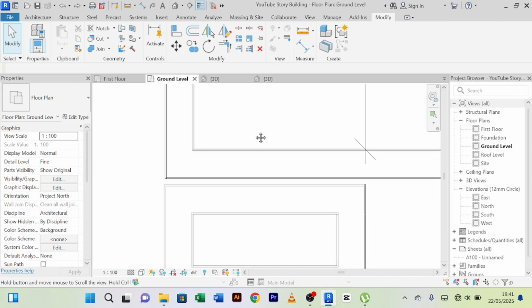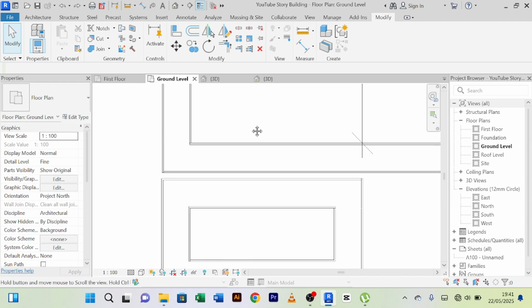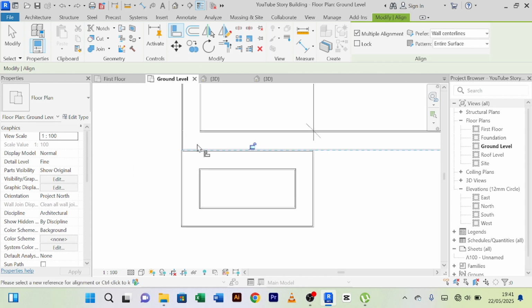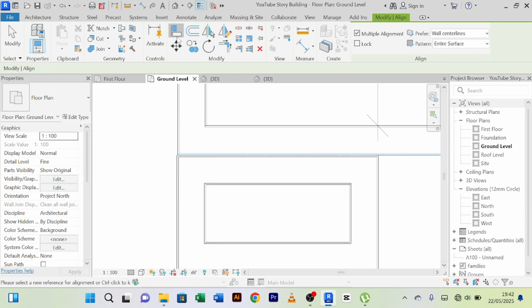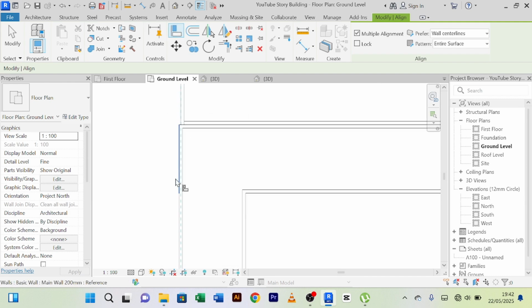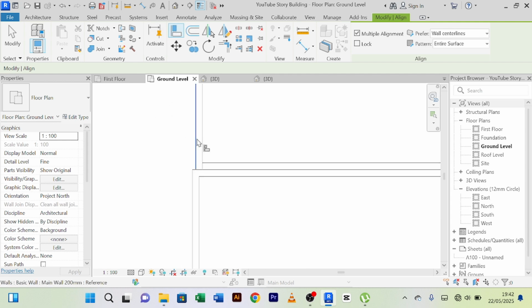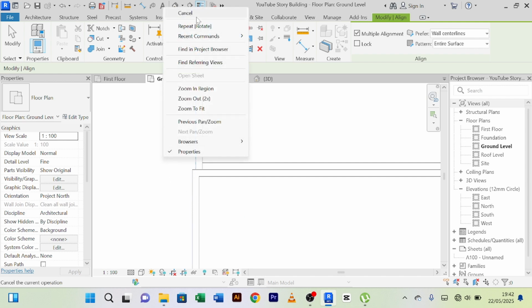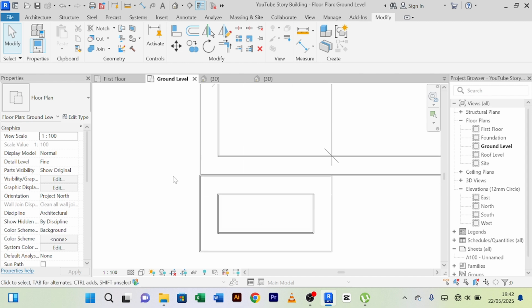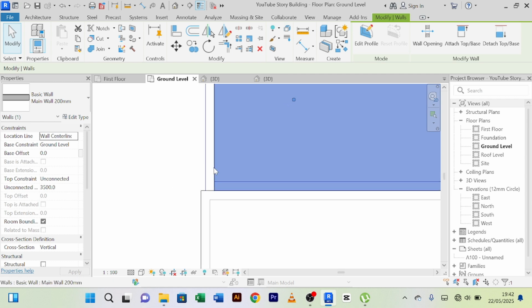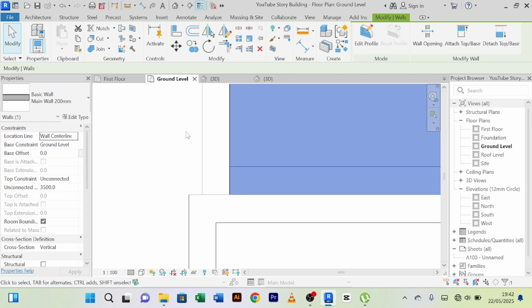So sometimes you can also do these things manually as long as you are achieving what you want to achieve. So it's not always straightforward. Then this one, of course, we wanted 1000. We shall click on this wall, then give it 1000. Then the inside, let's see, the inside is 389. We wanted 350, so we shall put here 350 like that.